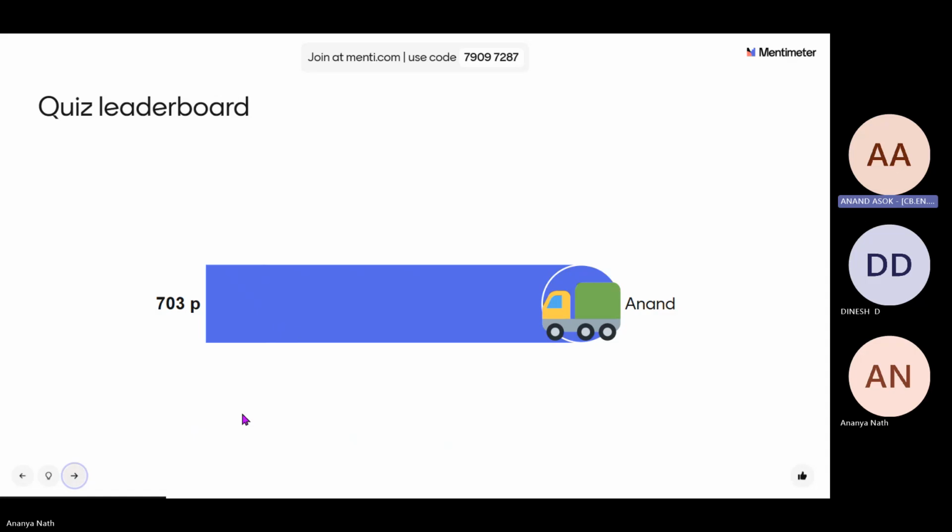So if the layer is big, that means the pixel size will be less, is it? Okay, so now there is no relation between the pixel size and the layer thickness because pixels are constant. The screen you're putting below the VAT is there for the whole life of the printer, and the screen will have a definite number of pixels which can never be altered.